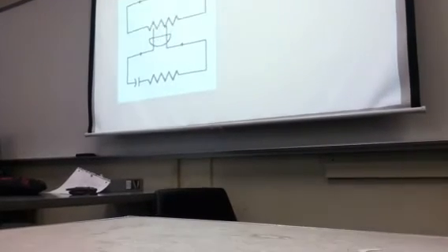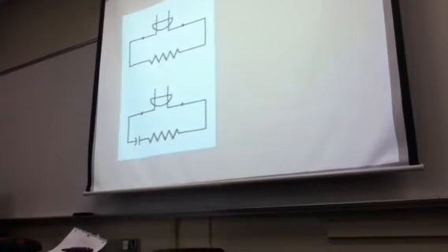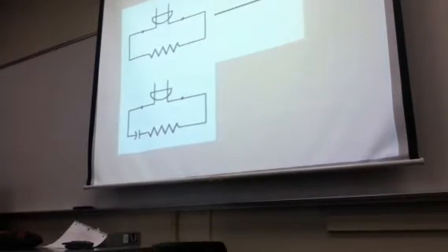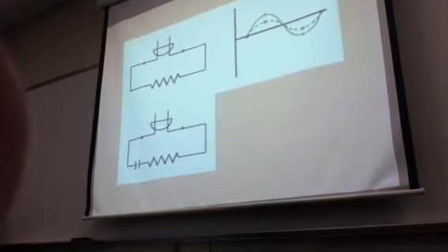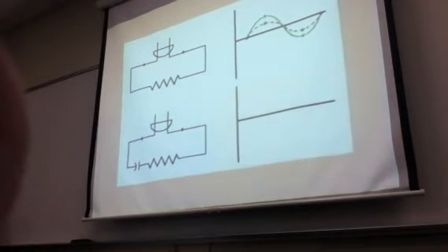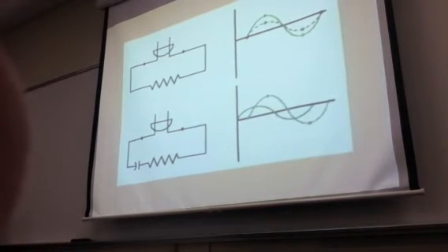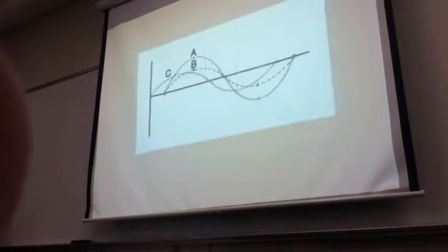We discussed capacitors in Module 6. Let's take a moment to review how capacitors work. In an AC circuit with a purely resistive load, the voltage and current are in phase. They peak and cross zero at the same time. When a capacitor is connected into the circuit in series with the load, current will lead the applied voltage.